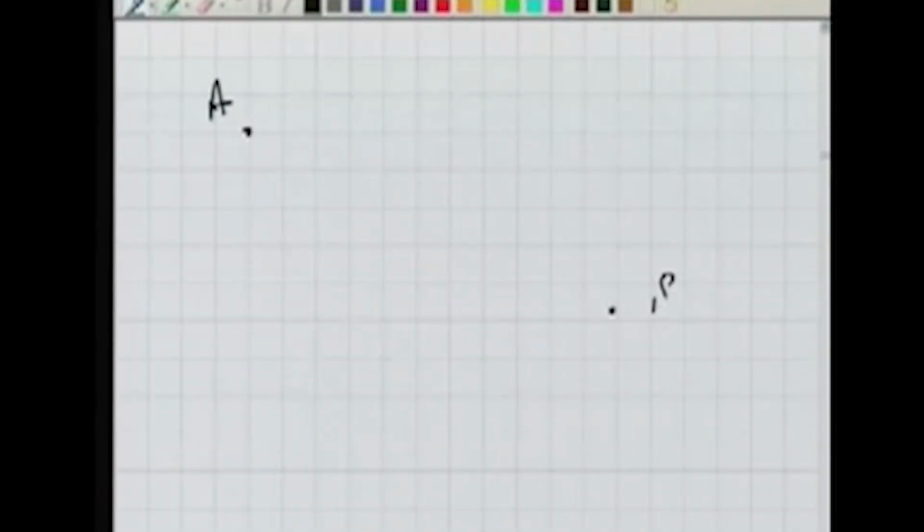In the earlier case we saw the line of sight will form an inclined plane, not a vertical plane. In this case it is not forming a vertical plane, rather it is forming a cone which is centered here and something like this. Now that is the problem. If that is the problem, what will happen? If you are taking the observations as in the earlier case, there is one object A, another at B at different heights, and somewhere here is the observer, and I want to measure the horizontal angle between A and B.